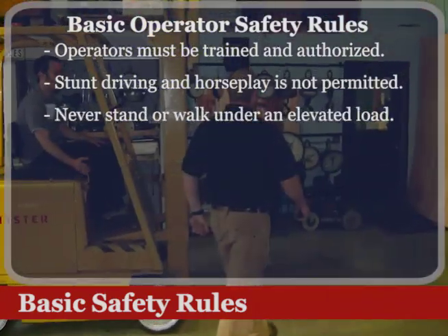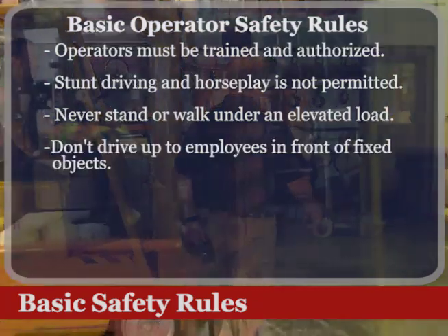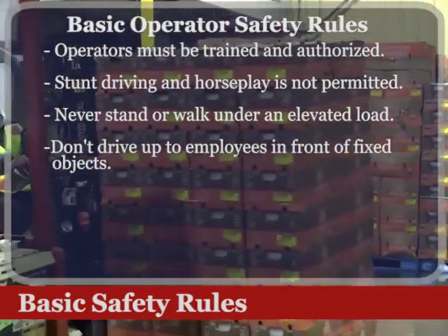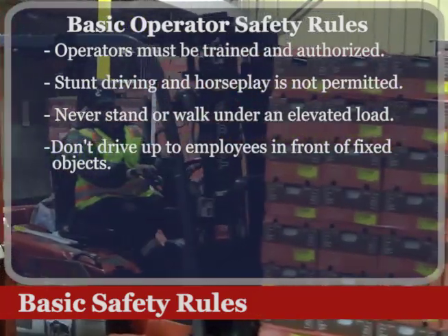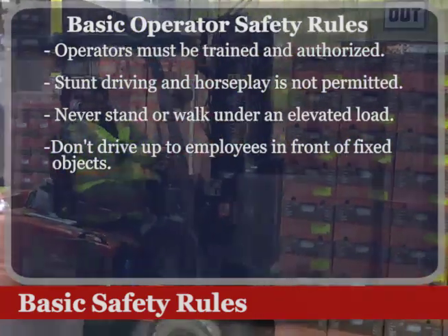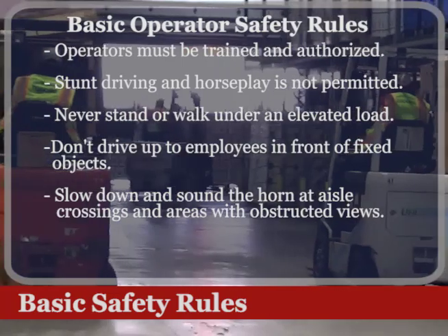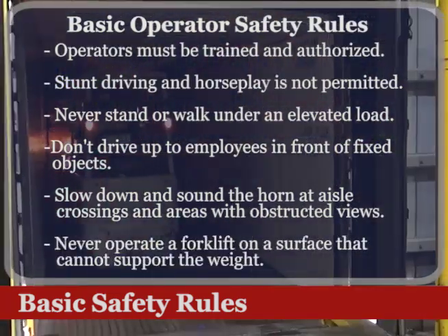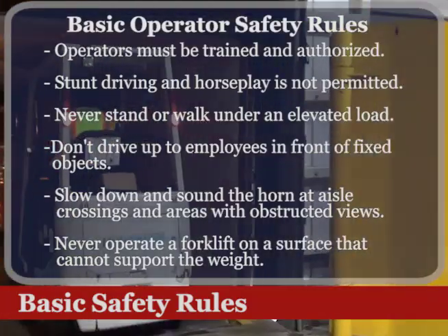Never stand or walk under an elevated load. Don't drive up to employees in front of fixed objects. They could get trapped between the object and the forklift and be crushed or killed. Slow down and sound the horn at aisle crossings and areas with obstructed views. Never operate a forklift on a surface that cannot support the weight of the vehicle.